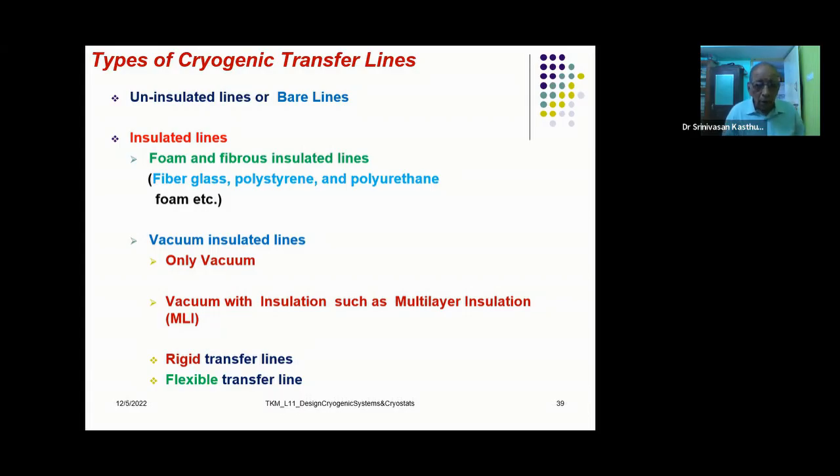These materials have low emissivity. Because of low emissivity, the incoming radiation is minimized as much as possible. An optimum number of insulation layers is chosen so that the heat transfer by radiation is minimized, and at the same time, conduction heat transfer does not go to very high values.